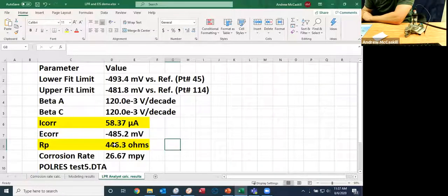So in this span of time, I think my system is still trying to get somewhat equilibrated, and the initial corrosion happening on the surface is probably slowing down ever so much. But still, I expected much higher values compared to what I had yesterday. I can already think of steps I probably could have taken to improve the surface, and I think polishing the surface probably would have helped out. There's a good chance if there's some rigid areas in the area I exposed, then that could cause corrosion to happen quite rapidly. So shame on me for not sample prepping as well as I probably could have.